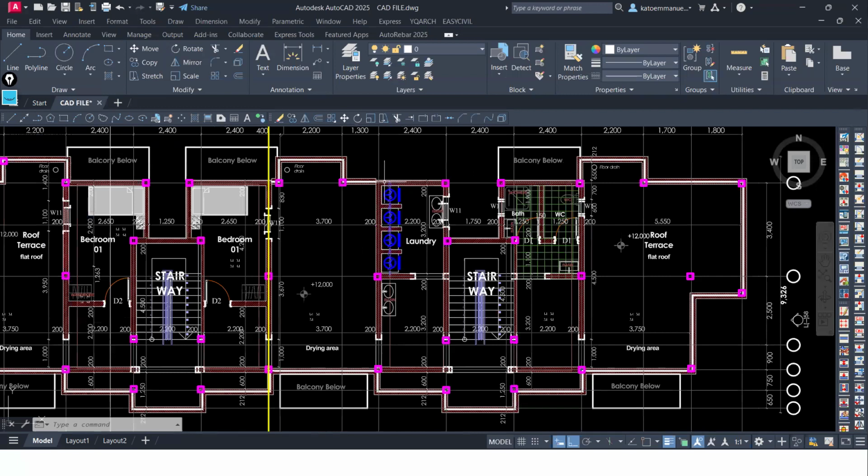So since it is the last level, I can factor in that before casting those beams, the ring beams, you will first have walls. Then the walls will support that beam. You get it? But if it was at an intermediate level, that would not work.